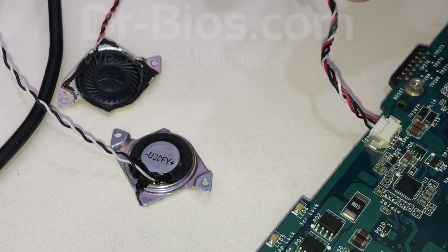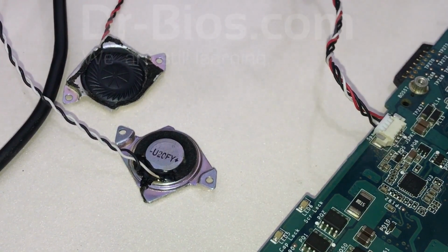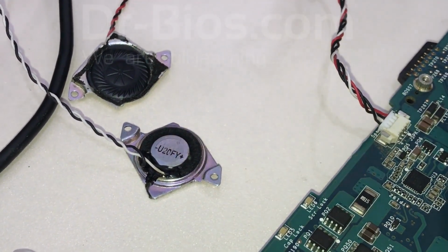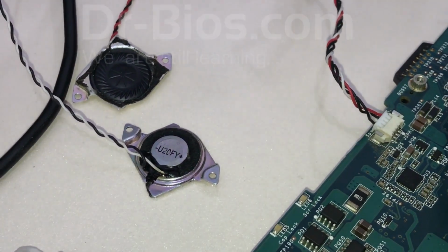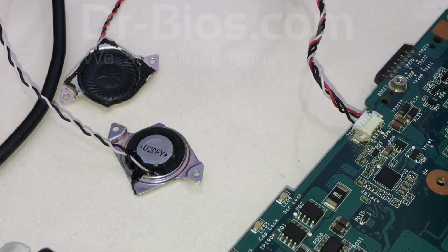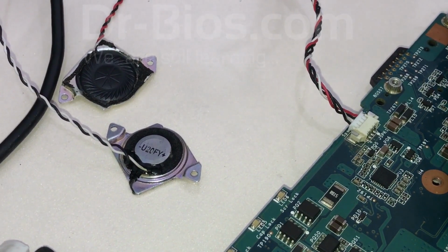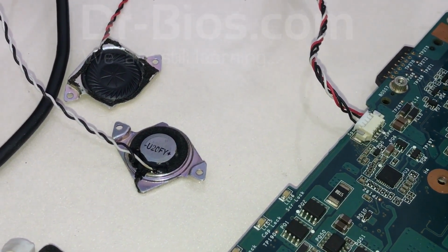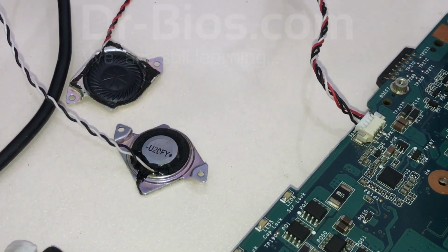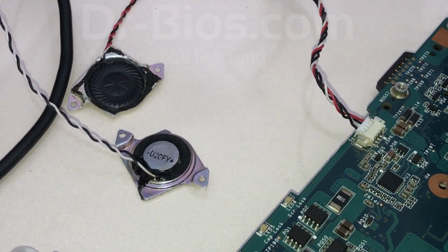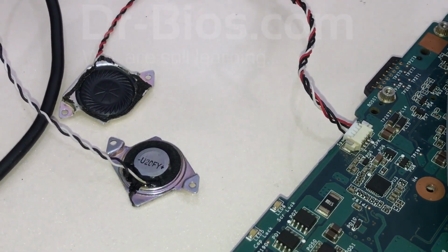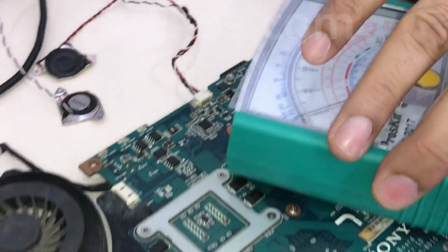Because you need to place the new speaker in the old speaker's block. After that, the things you need to be careful about are wattage and ohm amount. But let's assume you don't have a 4 ohm speaker. You can use an 8 ohm speaker. It's not vital, but it's better to use the exact same ohm amount, because the amplifier circuit is designed with the ohm of the speaker. So it's better to use the same ohm amount.